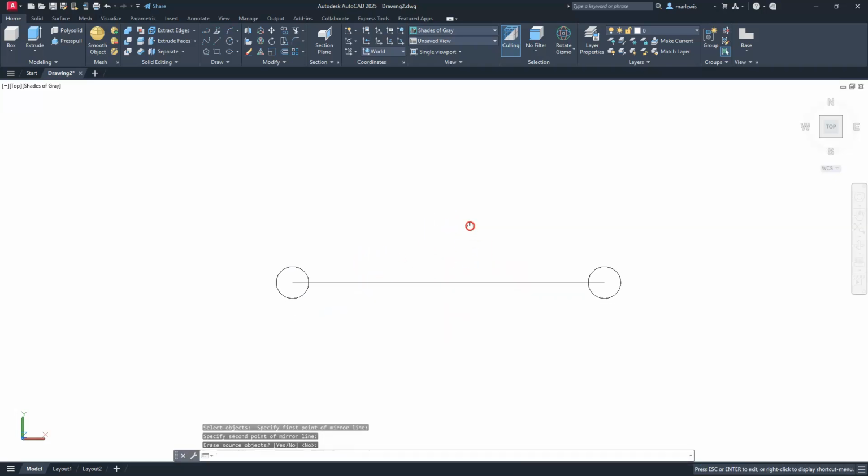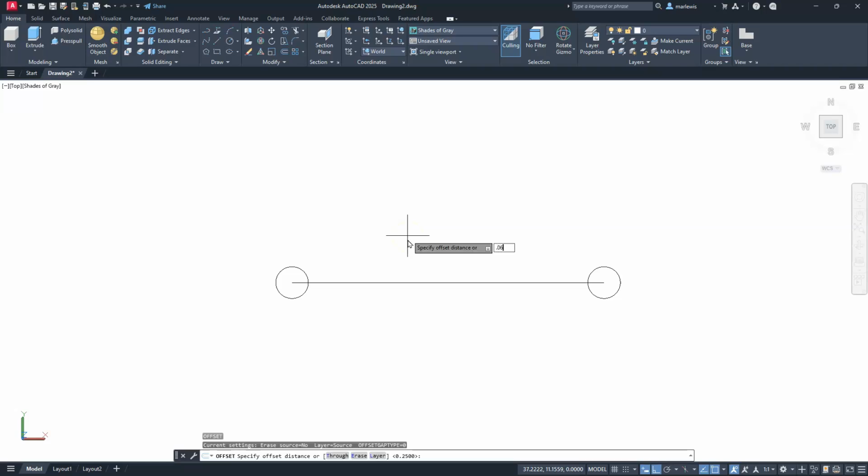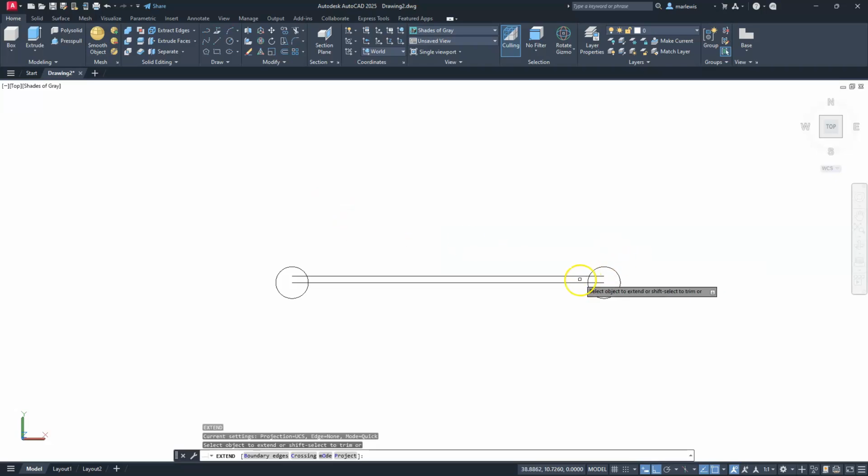All right. Do a little bit more work to this. Let's offset this a distance of 0.0625, which is 16ths. A 16th, so offset 0.0625. This number is actually half of the thickness of this. All right, let's do an extend. So we're going to extend to here. And now while I'm in this command, I'll just hold down the shift button and that should take me to a trim. So kind of combining these commands, keeping them all into one.